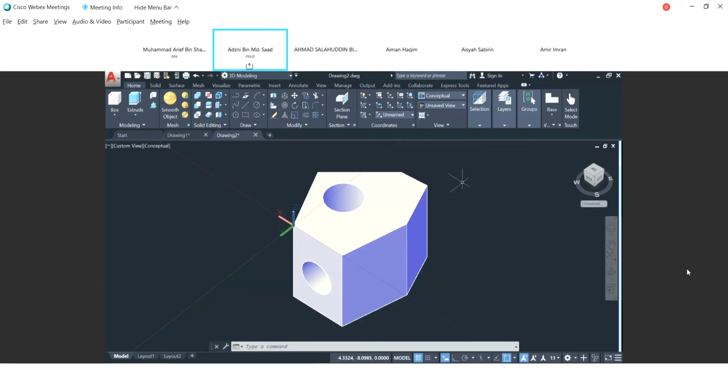If you want to construct another geometry on another plane, then you need to change the orientation of that plane to become your XY plane. The same thing, for example, if you want to do something on this plane here, what you need to do is move this X, Y, Z axis to be on this plane, and then change this plane to become your XY plane. What you can do is click this XYZ axis, click the origin and drag it. Make sure it's right on the plane you already selected.